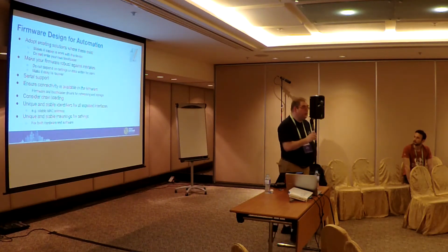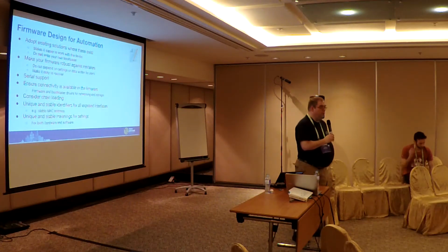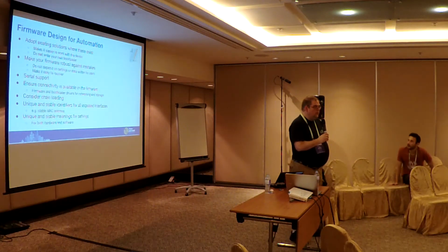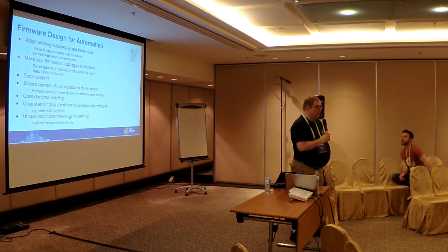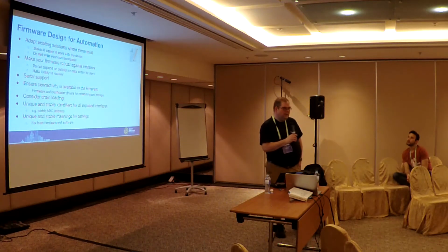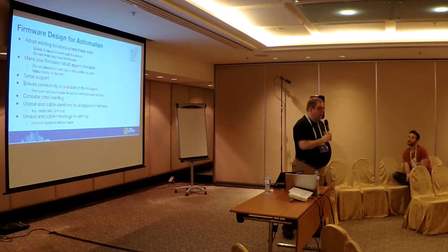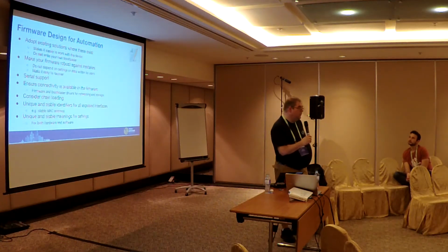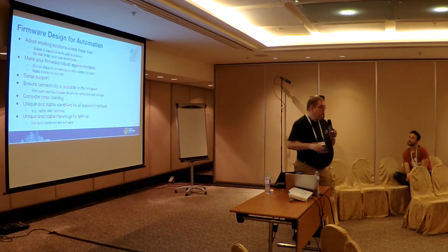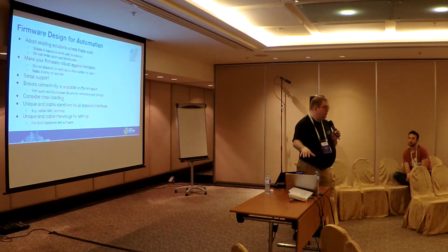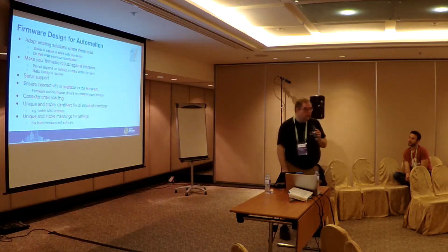So it's not firmware, bootloader. Do not write your own bootloader. It's like, don't write your own crypto code. You might think you have a compelling reason. I 99.9% guarantee you don't. You just don't understand the problem. If you write your own bootloader, it makes it so much harder to automate your device that this is the hardest part of what we have to do when we're working with something new. Please don't.